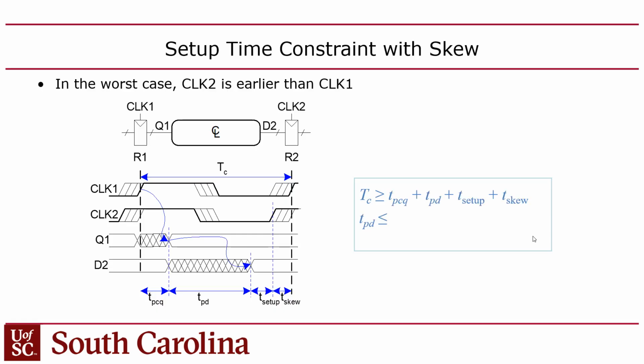Okay, so basically the way that you take care of this is, the clock skew is another technology parameter. So this is yet another part of that 70 gigabyte download that you get from Quartus. It's defined for every FPGA technology. It basically depends on the size of the FPGA and the technology of the clock buffers and how big the clock tree is.